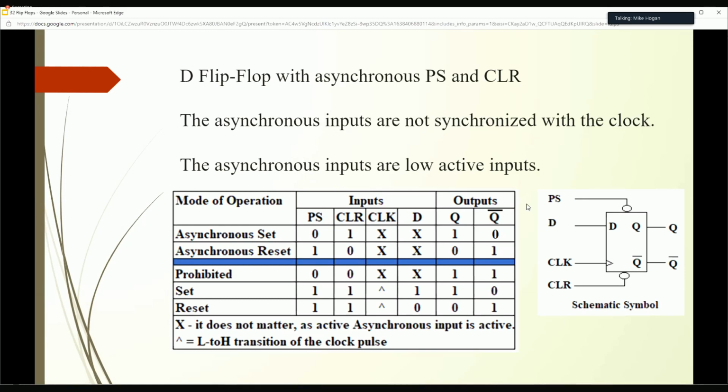So as I've got a clock pulse feeding into this, and I've got data coming into this, I'm going to be able to, once again, lock in or latch whatever this bit is, and then I can hold it so that I can perform some function with it later on. And so this is what we're talking about with these flip-flops, these latches. It's just a matter of holding a piece of data, a binary bit, so that I can use it in typically a calculation or something at a later point.